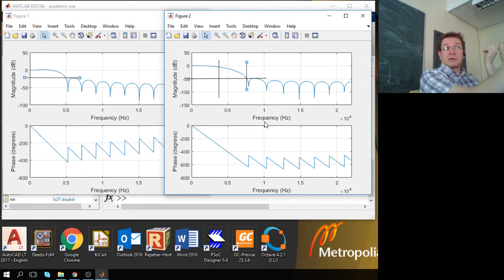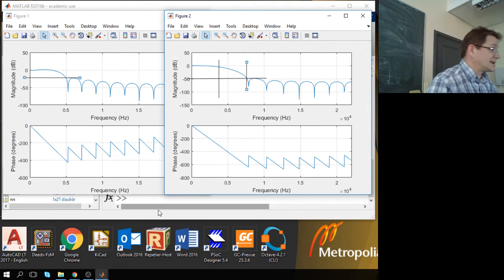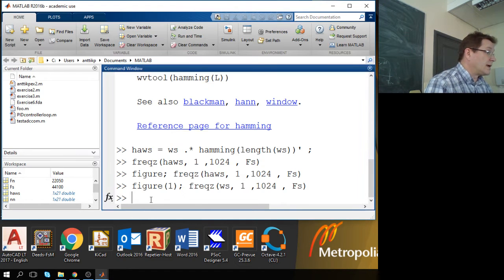We can control the cutoff frequency by selecting the sinc, then the stop band attenuation by selecting the window shape, and then we can still increase the time, meaning take a wider sample, to decrease the transition bandwidth. So for example, if that transition bandwidth cannot be more than say 1 kilohertz, let's take a couple of values here.